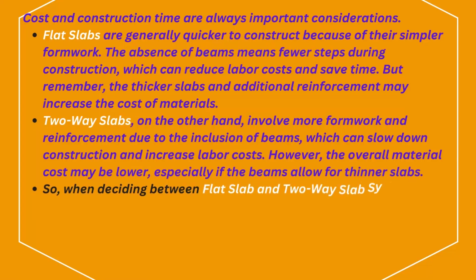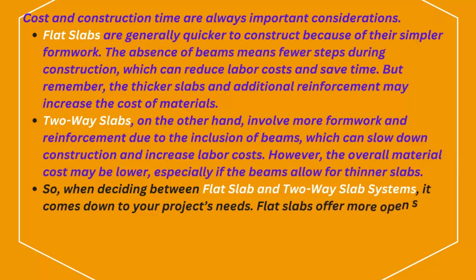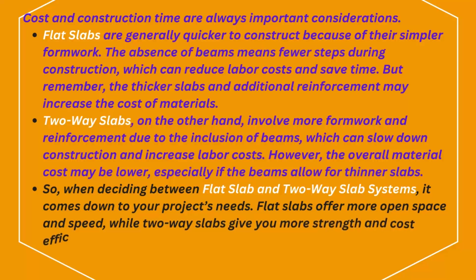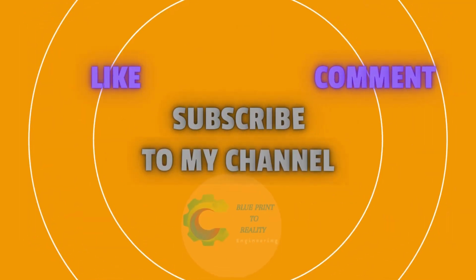So, when deciding between flat slab and two-way slab systems, it comes down to your project's needs. Flat slabs offer more open space and speed, while two-way slabs give you more strength and cost efficiency in certain designs.